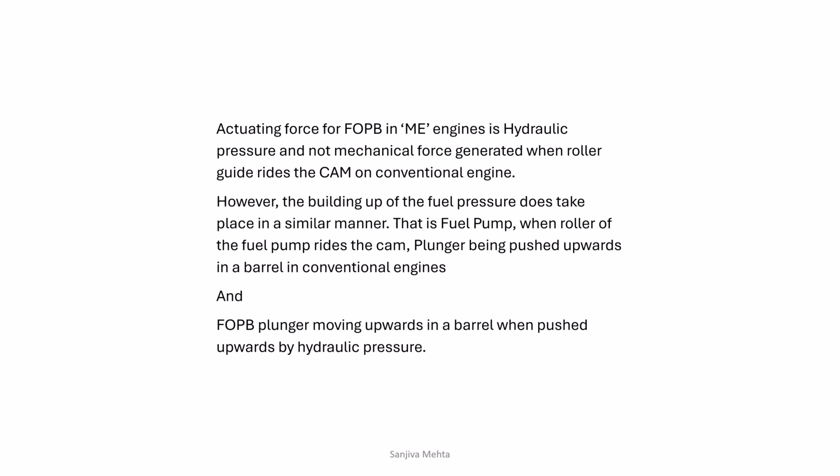The actuating force for the fuel pressure booster, the equivalent of the fuel pump in the ME engine, is hydraulic pressure and not mechanical force, which is generated when the roller guide rides the cam on a conventional engine. Here, hydraulic pressure is generated by the hydraulic pump, variable delivery piston pumps. However, the building up of the fuel pressure does take place more or less in a similar manner.